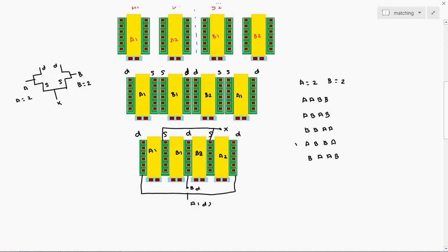This pattern is the best because of this schematic. Because the source terminals are shared here, I can easily merge source and source terminals, then reduce the distance between the transistors and shrink the area without affecting the performance of the channel. So choosing the pattern is based on the schematic only.